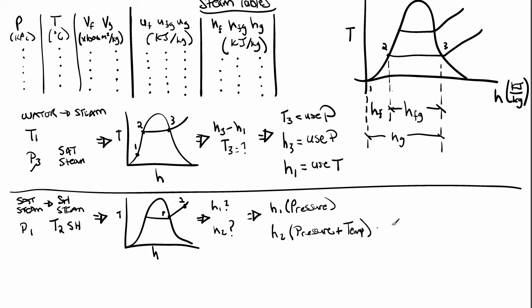So we'll go through an example of those superheated tables at a different time. But I really want you to realize that in these situations, P1 equals P2. And above here, P2 equals P3. All these operations take place at constant pressure unless they tell you otherwise.